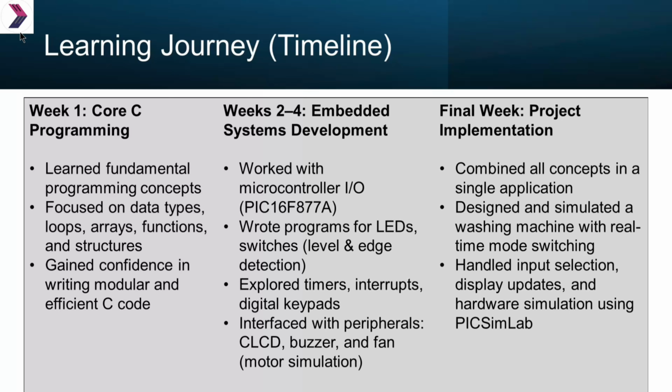Then in week 2 to 3, we learned about embedded system development, in which we worked on microcontroller input output, which is PIC16F877A, wrote programs for LED blinking and switches, and in switches we learned about level and edge detection. Next we explored about timers, interrupts and digital keypads, and interfaced with peripherals like character LCD, buzzer and fan for motor simulation.